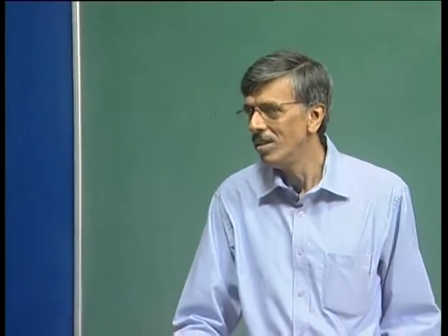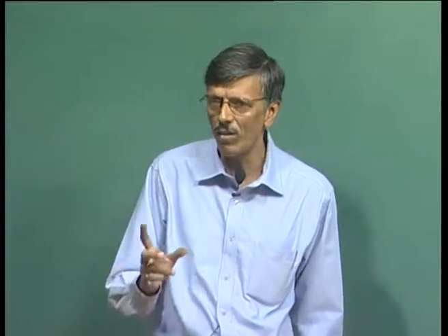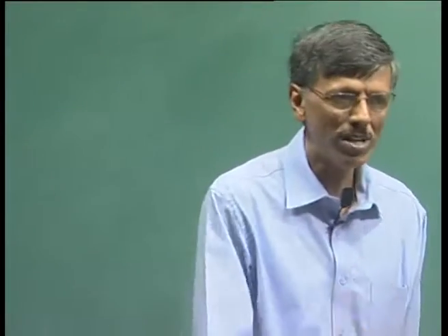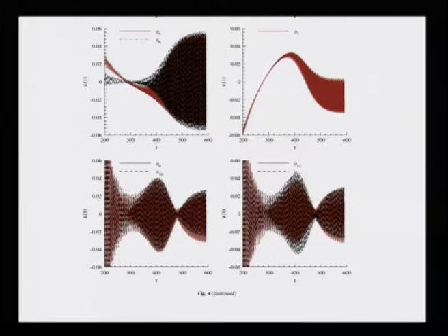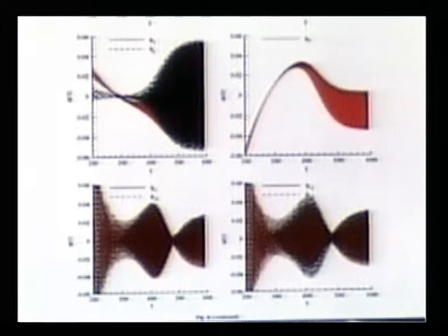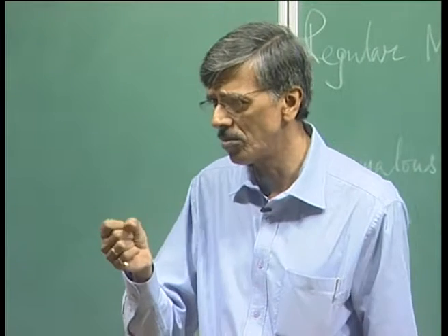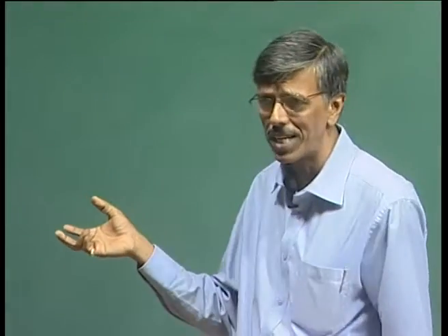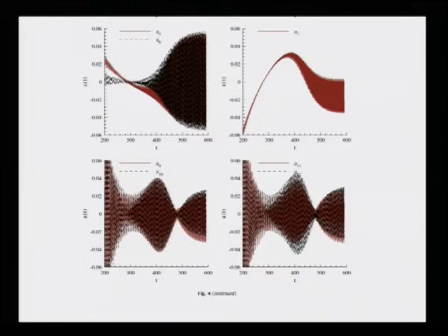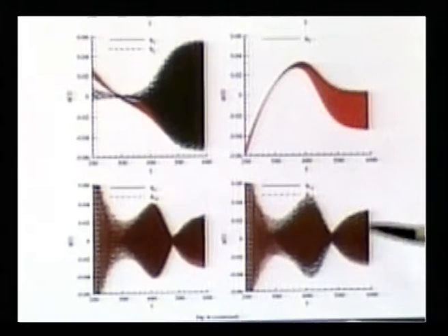And then of course, the moment you decide upon the sampling rate of POD analysis, that restricts you to what you are seeing. And tell you what, this kind of simulations have been done to pick up this kind of frequencies. What you are seeing here, we have shown it from 200 to I think 600, that is what we are showing. So, here the sampling time interval is of the order of about 0.01, 0.02, that kind of a thing. So, you can imagine the volume of data that you will have to handle to do a POD. And if you do not do it, of course, you will not pick up all these frequencies.